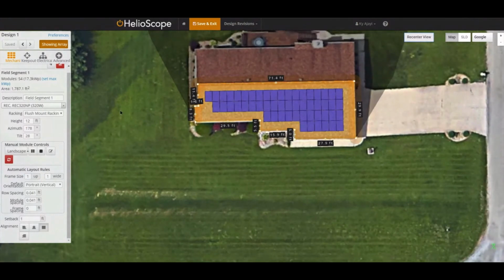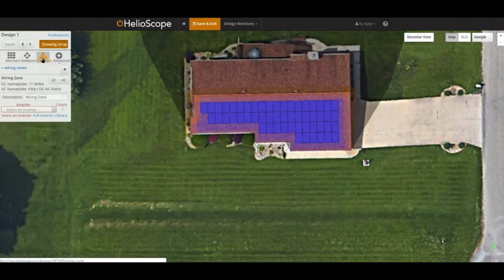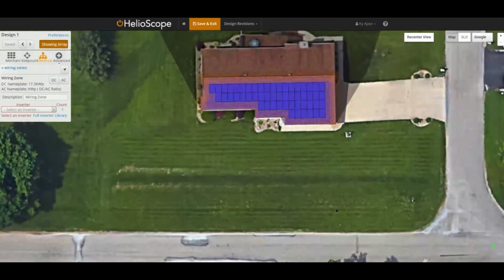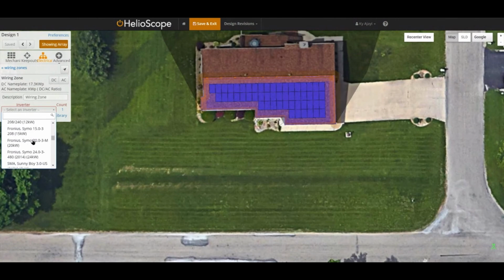The next step is to pair this with an inverter. The modules are producing DC power, and we use AC power in our homes. So typically we will use an inverter that will convert that DC power into AC so it could be used in the home. If I click over here onto my electrical tab, since there are no obstructions to the south of this home, I don't expect there to be much shading. So that guides my choice of inverter to the SMA line of string inverters.